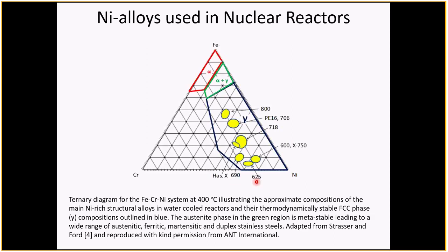You might mount flux detectors on a rod which is made of Inconel 625 or Inconel 600. So these materials you tend to see related to flux detector assemblies. Now, flux detector assemblies are usually interchangeable, and if they start to deteriorate after 4 or 5 years of service, they can just be changed.